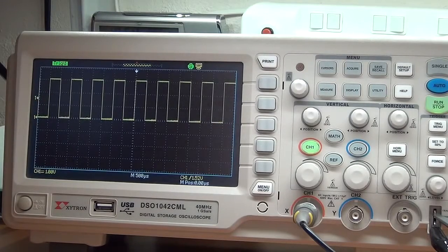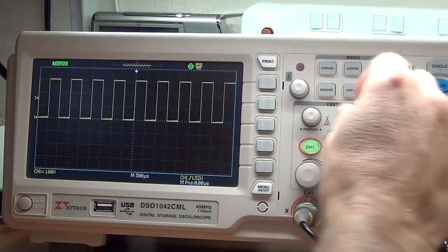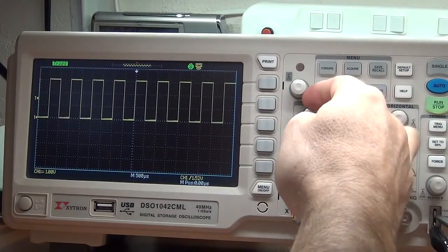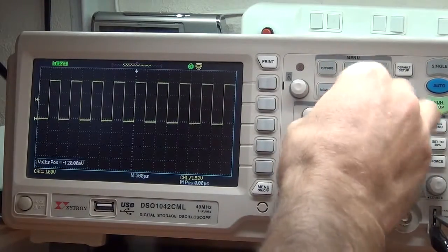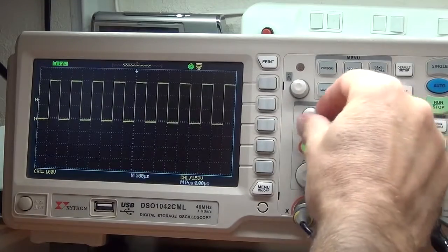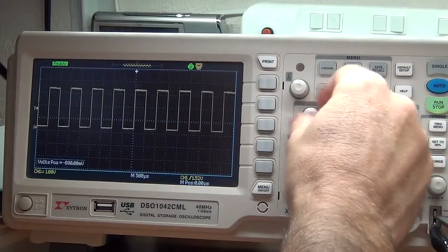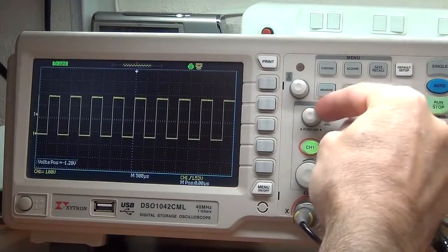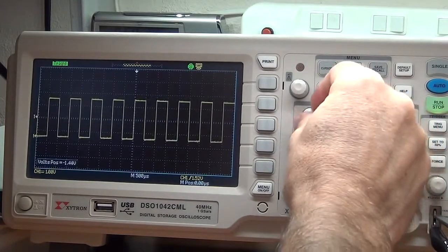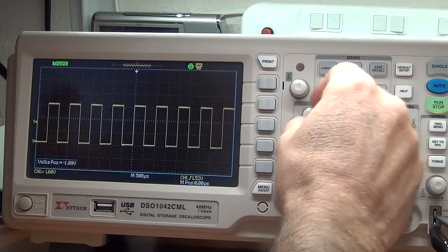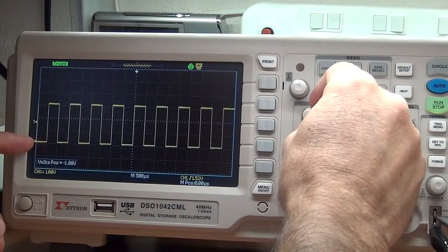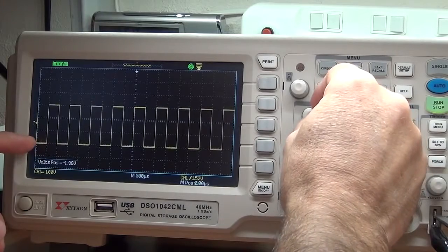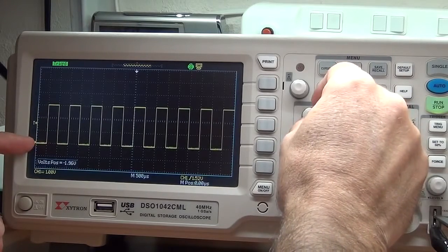Then if we look at the positioning, I can obviously move the signal down. I may want to have that signal down in the display at a middle point, because that's where I want to take some readings. And that's where this vertical position knob helps me move it. I could move it so that it sits nicely on these divisions, so I can make measurements.